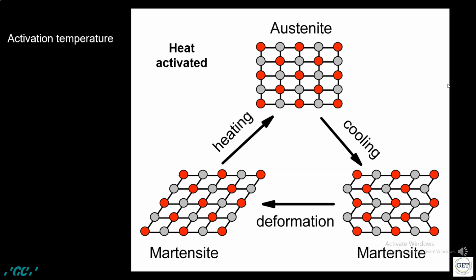The deactivation phase is initiated by the change of temperature, as the wire temperature is elevated by the mouth environment and reaches the activation temperature, the wire is activated and starts the process of returning to the austenite phase, back to its initial shape. This characteristic offers the user high flexibility in manipulation and lower forces. The level of forces and the deactivation temperature can also be controlled by the manufacturer.